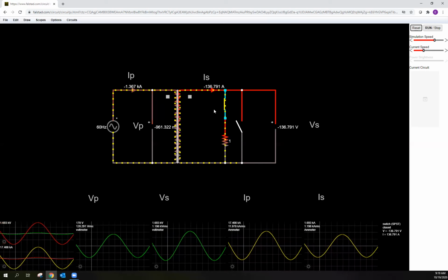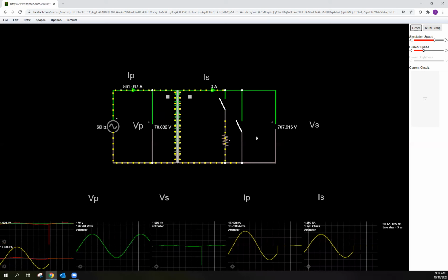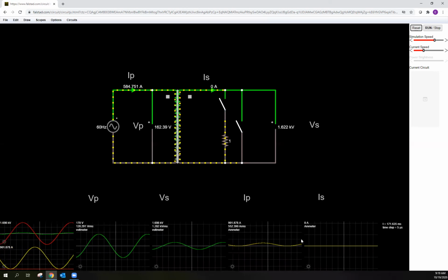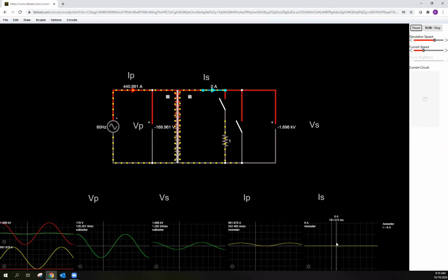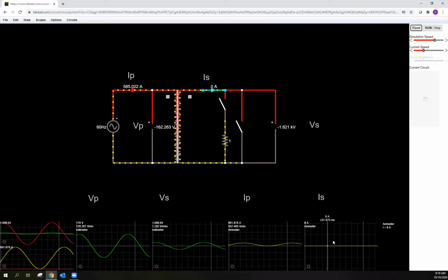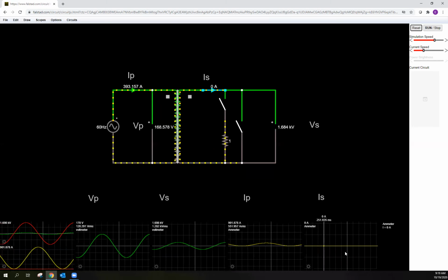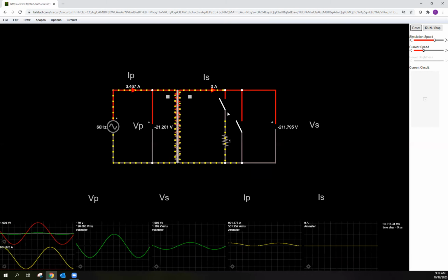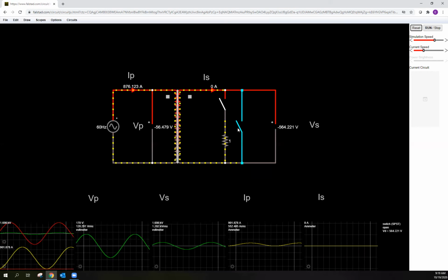Oh, one thing we could do is just double check this. Notice I have an open circuit here. Obviously, the ideal relationship isn't holding, right? I have no current on the outside, right? And the relationship would say the secondary current is equal to N1 over N2 times I primary. Well, obviously, in an open circuit on the outside, that's not going to enable that. What if we short circuit it?